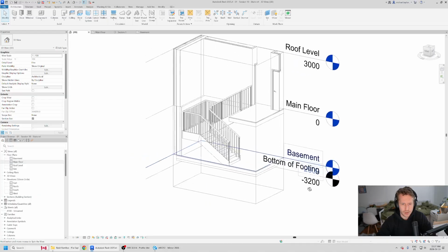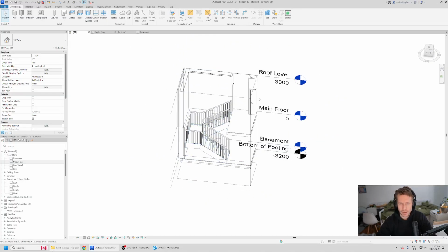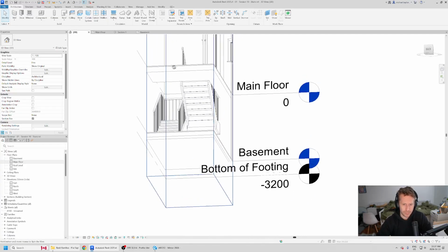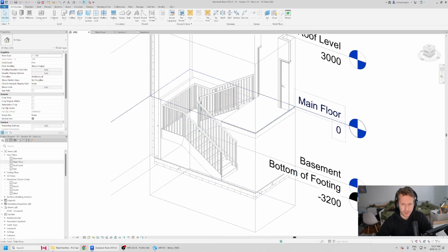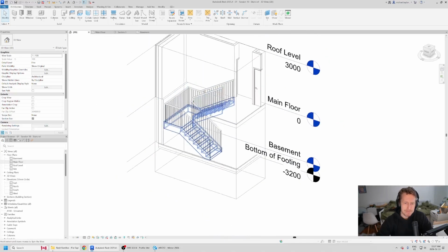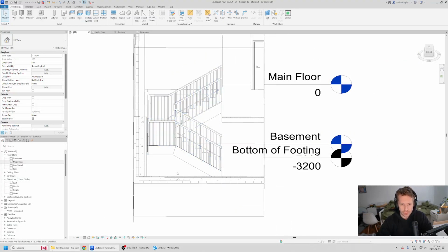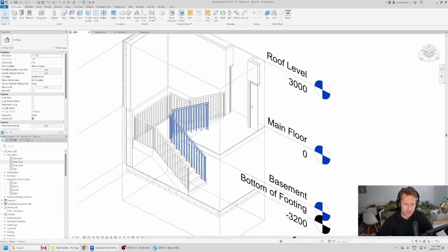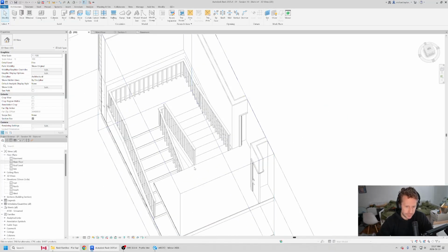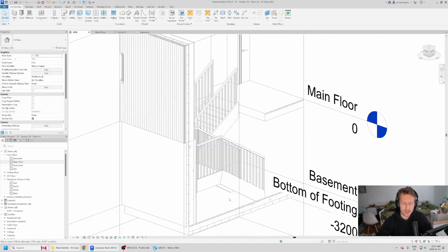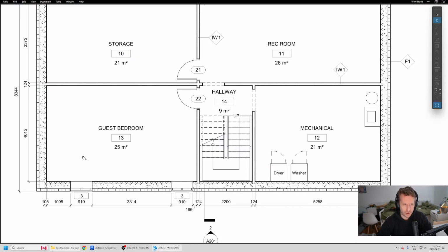We've got a code-driven stair with all of the information that we might need for elevations coming from the main floor and the basement. We've got information about the number of risers, number of treads, what the material is. We've got lots of information here. One thing that's missing, this little edge here, someone can just fall right off of here, right? So being mindful of how guards work in stairs is also part of our job.